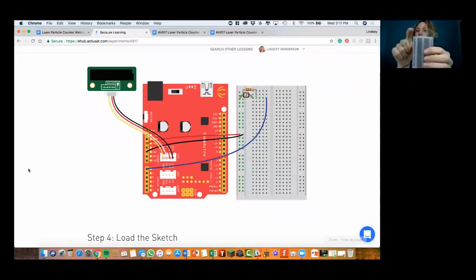Okay, do you notice that there's a positive and a negative on top of the rails? We are going to use that for our positive and negative wires in our Arduino. Now in my diagram, I'm going to take my red wire here, my positive connection. In my diagram, it looks like it's about on hole 11, the 11th row down. Remember, all of these are connected in a column, so it doesn't matter where I put it in that column, just as long as I get it in somewhere in that first positive column on my breadboard rail.